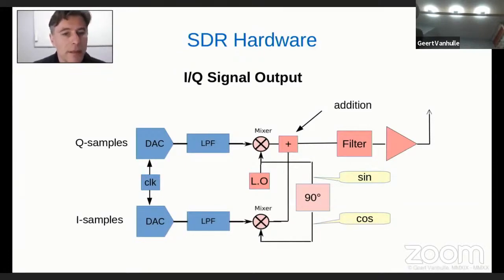However, here it's a little bit different. Although the circuit appears to be quite similar, there is a little difference here, where in the sampling circuit we had the same RF signal feeding into the 2 mixers. What we have now here is an analog addition circuit to add the 2 results of the mixers up. So we get the addition of the 2 mixer outputs. And now I won't do the mathematical functions here. You can do it for yourself. The formulas are in the previous slides.